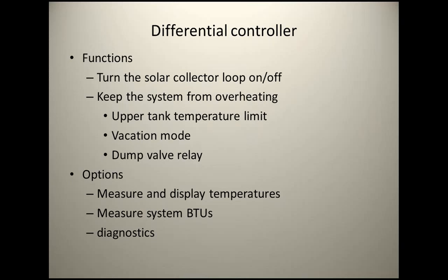Do any of the solar thermal systems have a mixing valve on the outlet of the tanks so that you add cool water to make sure you're back at the same temperature? That's essentially what happens with the dump valve. What you're doing is you're dumping the hot water, and cold water comes in to replace it from the city. So you take hot water from the tank, you run it through a mixing valve so it's only 120.